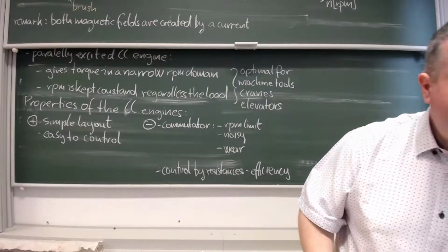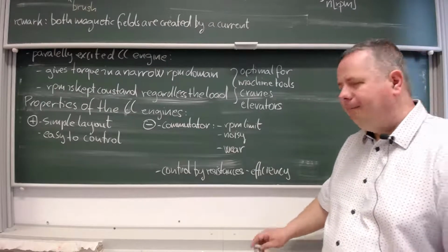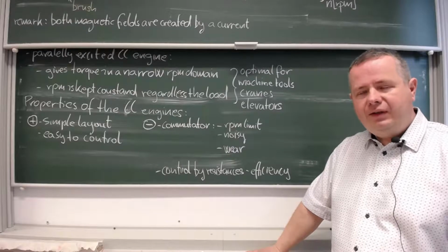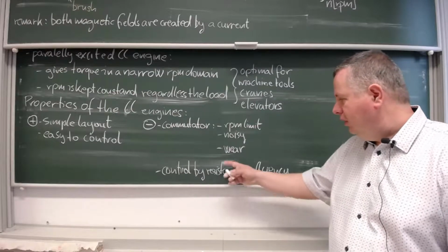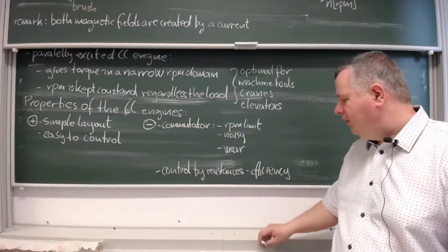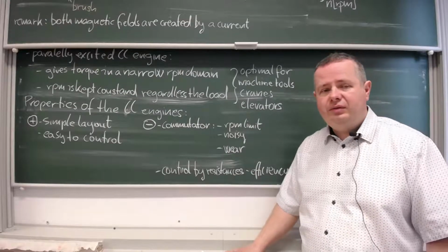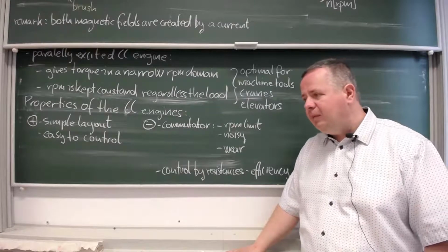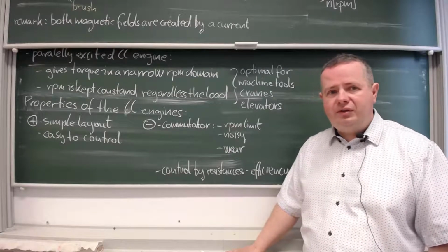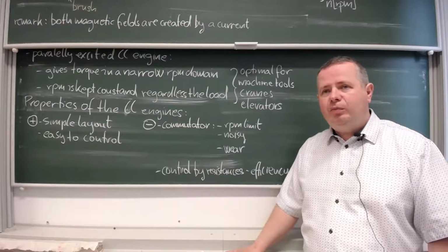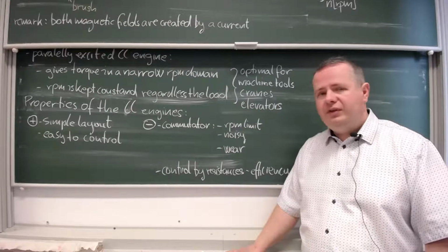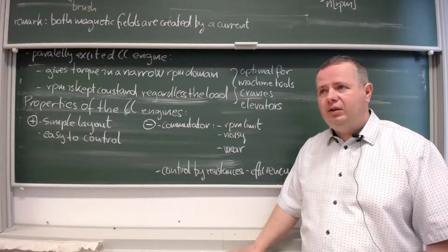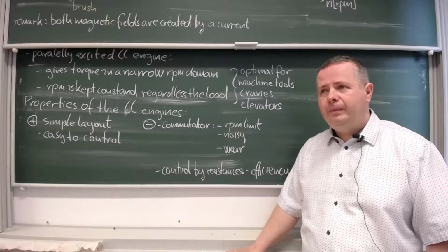So the second disadvantage of control by resistance: it's less efficient because of the generation of heat. Exactly. So the problem here is the efficiency, because the resistance makes heat, so the power is lost for making the heat. If we use other types of control device, using transistors or anything else, we get a much better efficiency for the system.